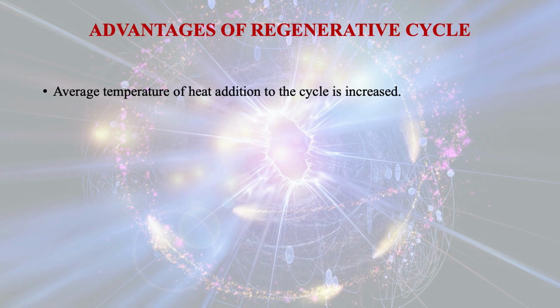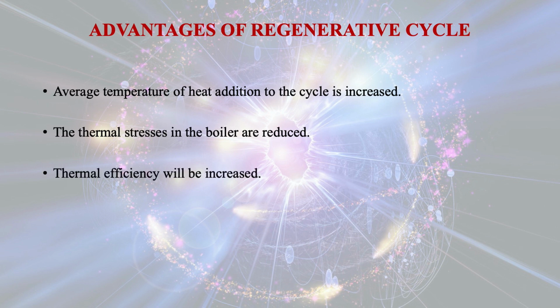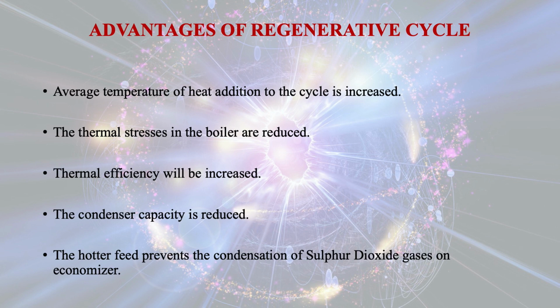There are some advantages of the regenerative cycle. The average temperature of heat addition to the cycle is increased. The thermal stresses in the boiler are reduced. The thermal efficiency will be increased. The condenser capacity is reduced. The hotter feed prevents the condensation of sulfur dioxide gases on the economizer.